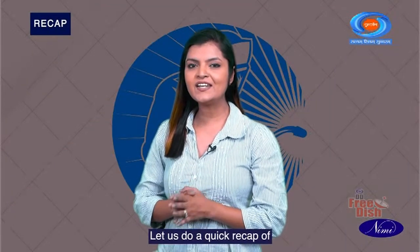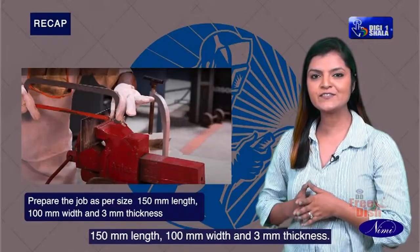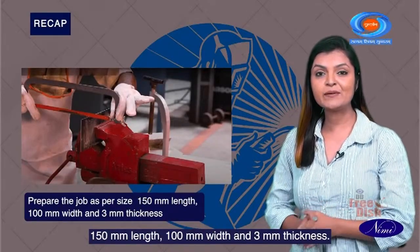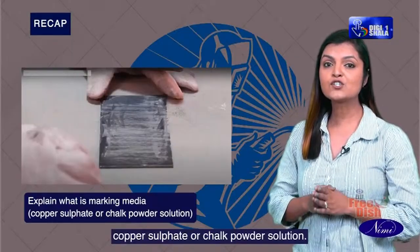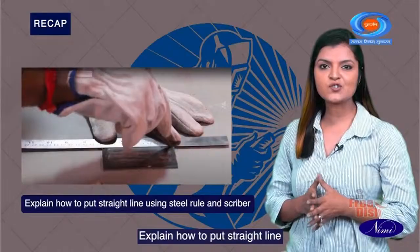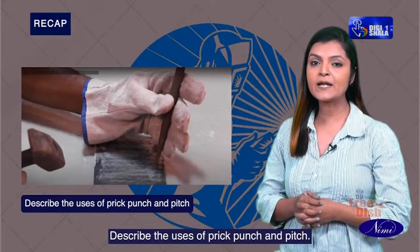Let us do a quick recap of what you have learned in this topic. Prepare the job as per size 150 mm length, 100 mm width and 3 mm thickness. Explain what is marking media, copper sulfate or chalk powder solution. Explain how to put straight line using steel rule and scriber. Describe the uses of prick punch and pitch.